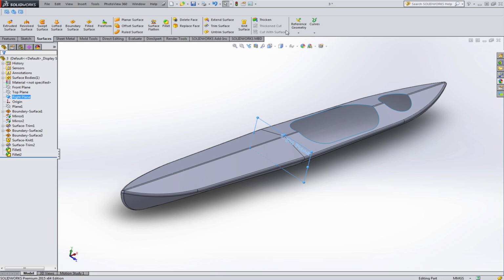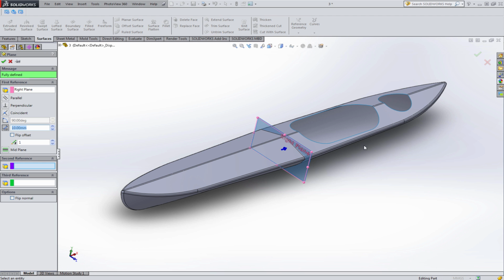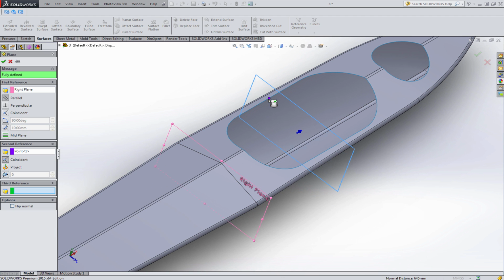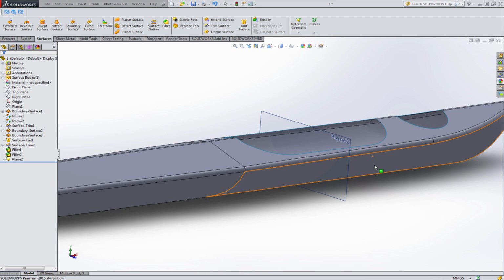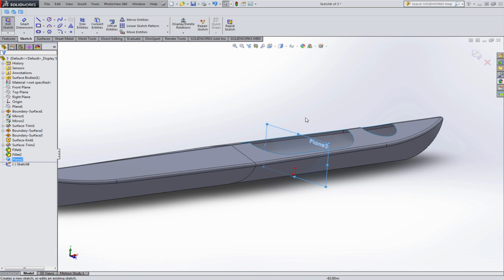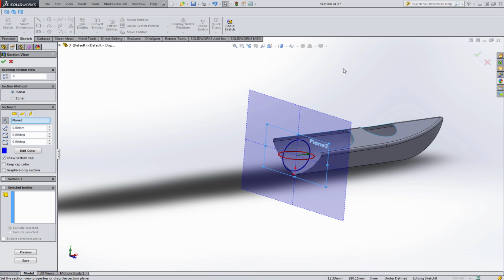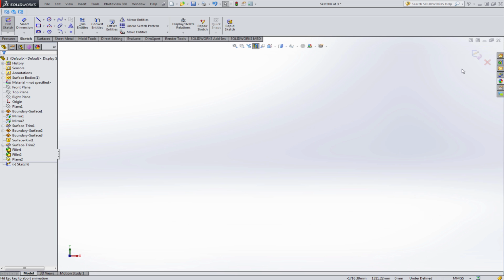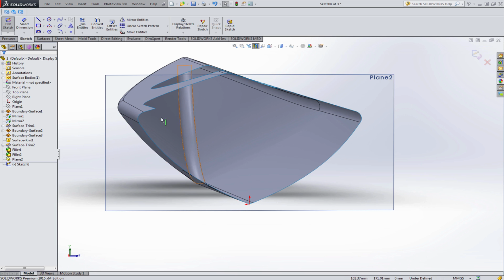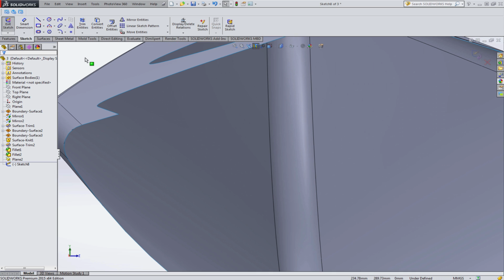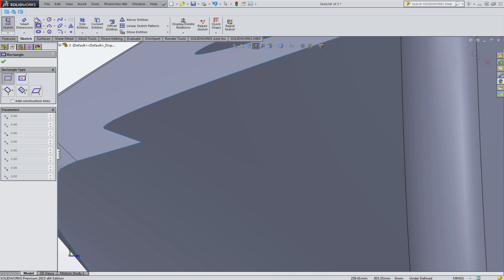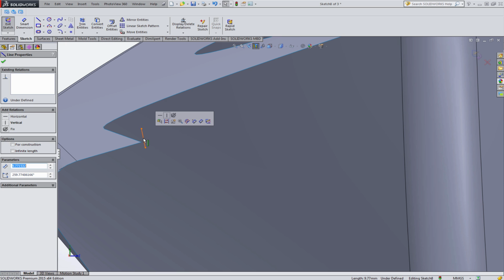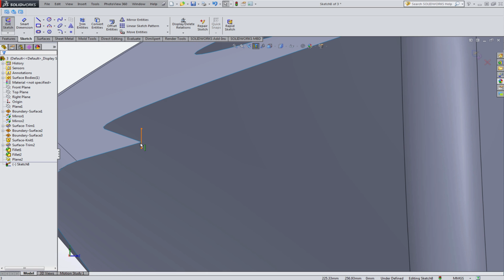The next thing I'll do is making of the curbs for the slot where the driver will be sitting. To create the curb, I will use the swept surface option. For this we need two profiles. One must be closed and will represent the bed, and the other one represents the profile of the curb. So this sketch represents the profile of the curb.